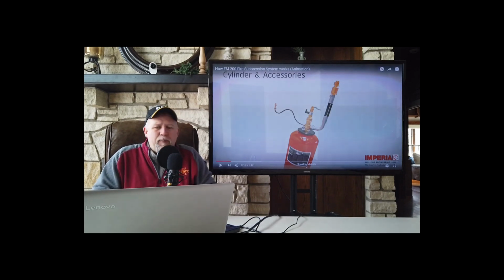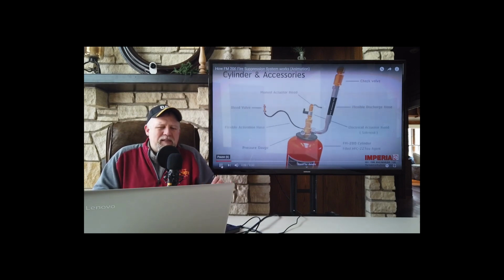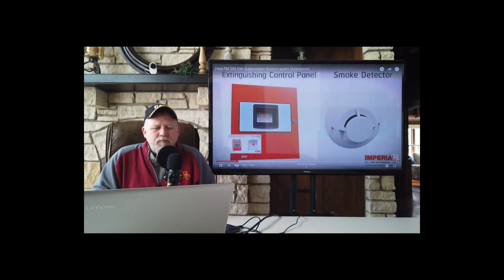I mean, if we look at Principal Financial, Wells Fargo, US Bank, any of these insurance or financial institutions, the data is the business. That is the valuable part. So if there is a fire in, say, one server, we don't want the fire suppression system to destroy it. So an FM200 system, where we have a gaseous-based system, that's going to be the type of system that we are going to install to protect a server room.